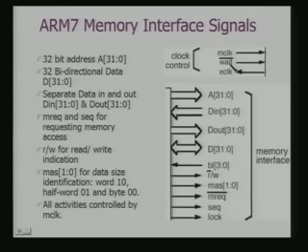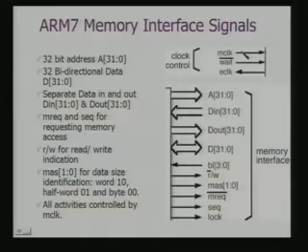When my memory is slow, for a memory access, the processor has to wait. So the memory module has to tell the processor, please wait till I provide the data. In that case, this wait signal becomes important. That is why I am saying that your internal clocking or internal operation is controlled through a combination of MCLK and the wait signal.